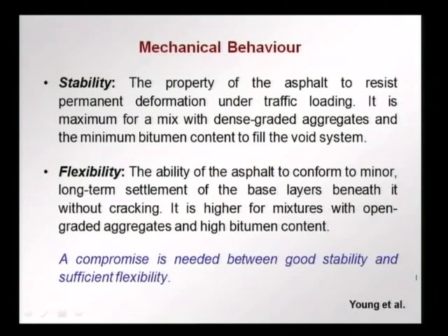So, we need a certain amount of bitumen and we have to fill all the voids. However, we cannot have a lot of flexibility because that will lead to a bumpy or undulating pavement.